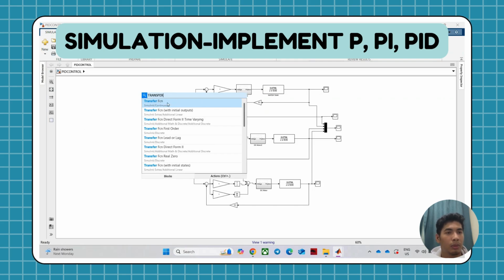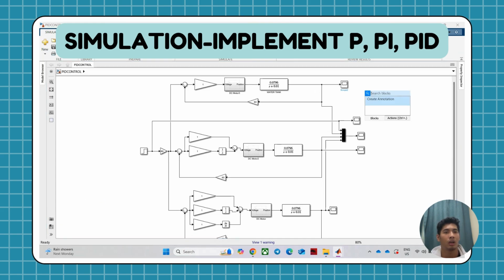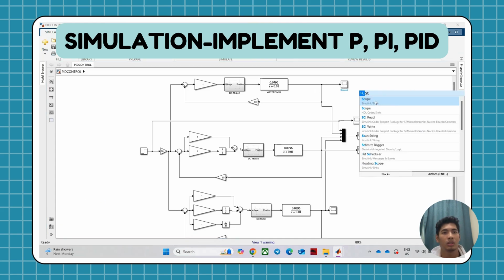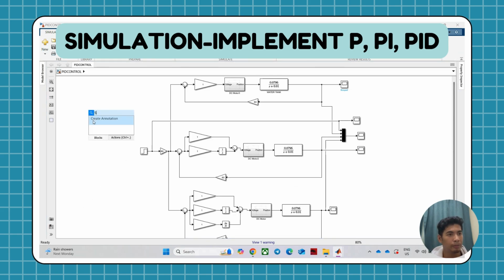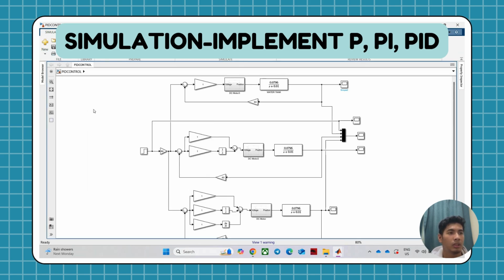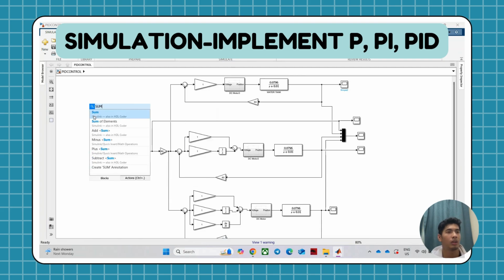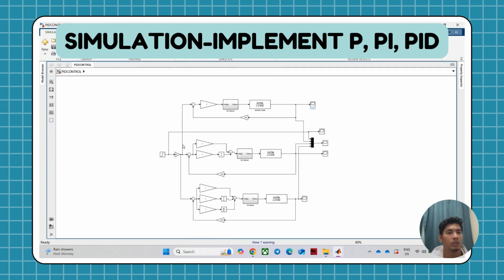So we get the block of the transfer function and put in our transfer function, and then we search for scope, step, and then this one is the summing block for the PID controller, and then we set up the circuit like this.